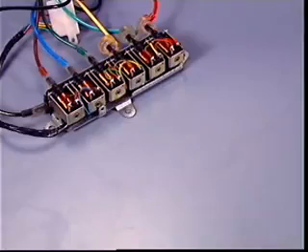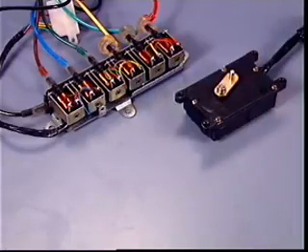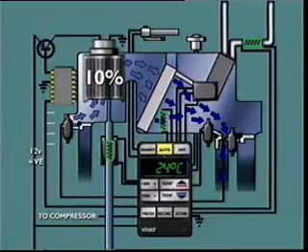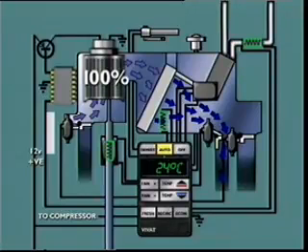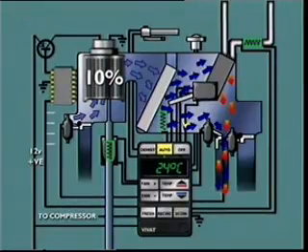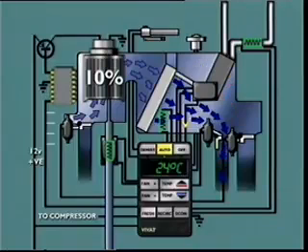The actuators are electric solenoids and electric motors which control the position of doors and taps either directly or by vacuum servos. The electronic control unit also controls the speed of the interior ventilation fan. The speed of the fan is infinitely variable between a stopped condition and the fan's maximum speed. Some actuators provide a feedback signal to the electronic control unit in the form of a voltage signal. This signal is used by the electronic control unit to determine what position the actuators are in and whether or not they are moving.